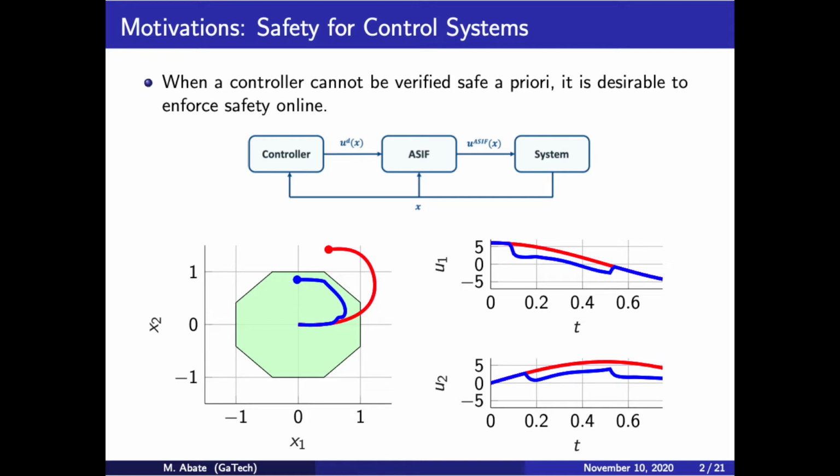So numerous methods exist for enforcing safety at runtime, and in particular, control barrier function-based techniques are well suited for this task. Certain control barrier function-based runtime assurance mechanisms even allow a system to leave its given safe set when safety can be verified by other means against alternate constraints. However, these methods do not yet account for systems with disturbances, and in our work we aim to build in this functionality and create runtime assurance mechanisms for systems with disturbances.